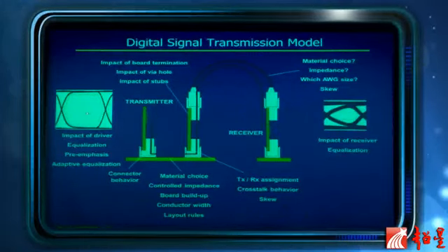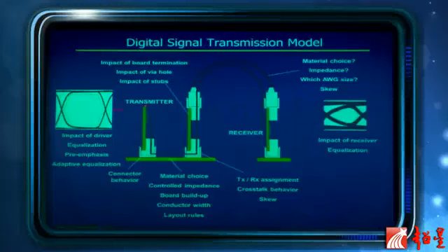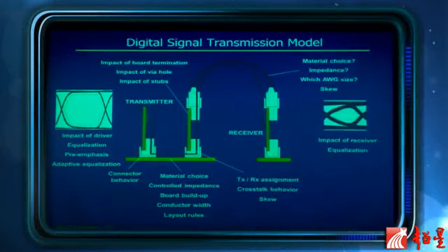The transmitter has a signal which should be very clean, right? So the eye diagram of the signal before it's been transmitted has a very nice eye diagram. You can see that logic high is right here, logic low is right here. The eye is pretty open, so we can recognize logic high and low.